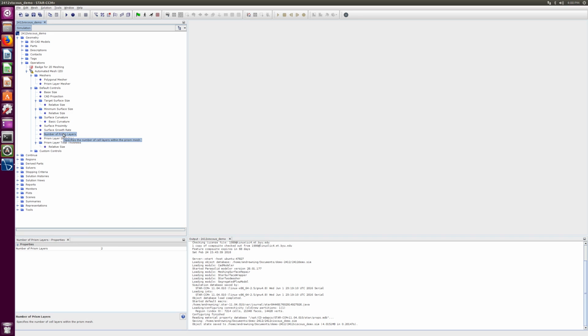So I did those 3 calculations already beforehand for the Reynolds number I want to simulate at. I'm going to do a Reynolds number of 5.7 million. The reason for that is because I have some experimental data that I want to compare to at that Reynolds number. So I did the same calculations we just looked at in that little presentation, and it turned out I got 35.8 for the number of cells, so I'm going to put 36 here. Stretching, the default is 1.5, but I like 1.2, something less aggressive.